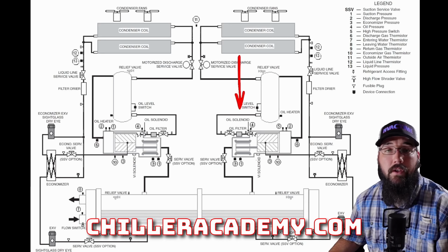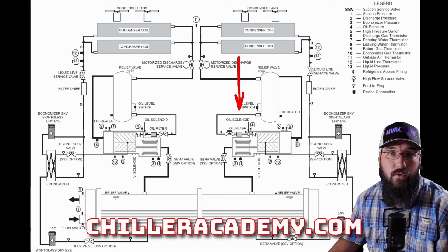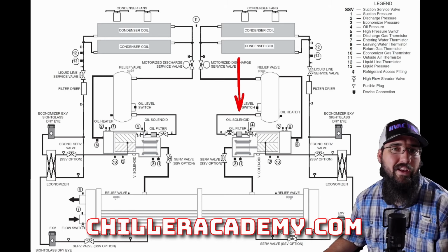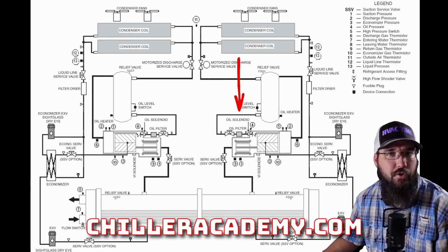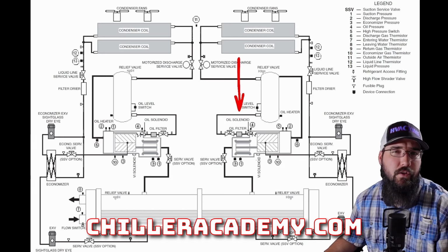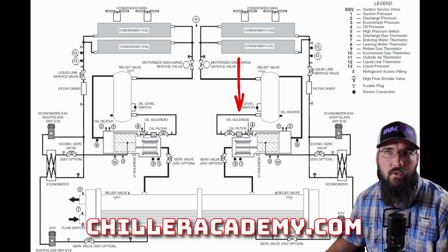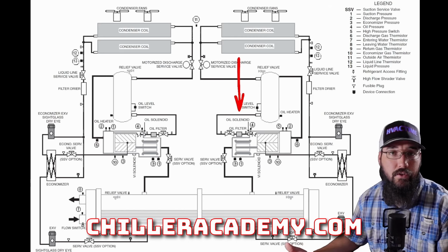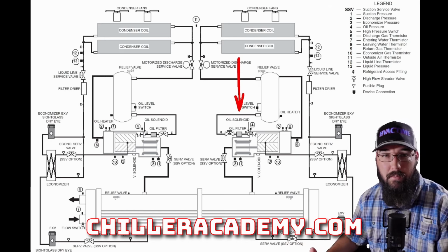So what about when we get into a multi-circuit or dual circuit, which it's pretty typical to see as many as 4? On a larger scale, you're pushing the 500 tons at that point. It just depends on the plant and how big a system they're running. A lot of industrial plants are going to have the larger 400 to 500 tons, which means you're going to be dealing with 3 to 4 compressors typically.